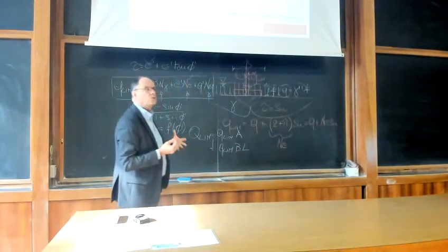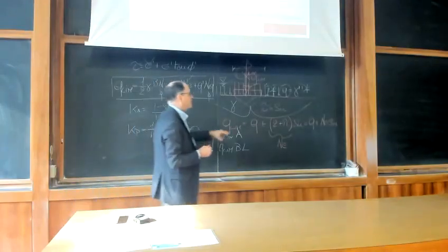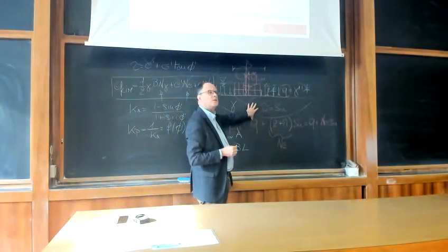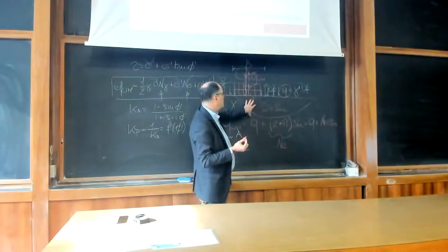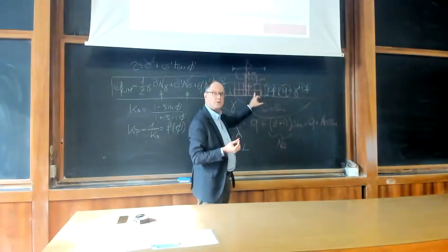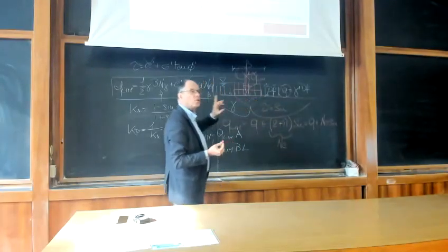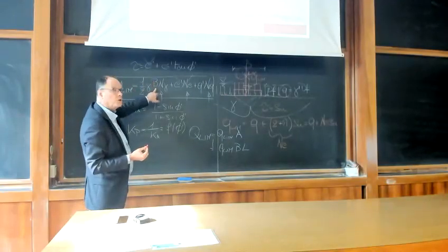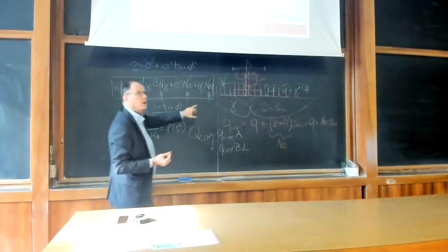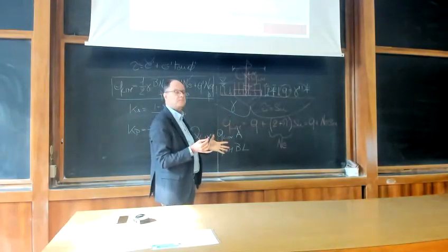So when you say, what is the bearing capacity of this soil, you can't actually answer this question, because this depends also on the type of footing and on the size of the footing you want to place. So you always should refer to the bearing capacity of your footing on your soil. The two things go together.